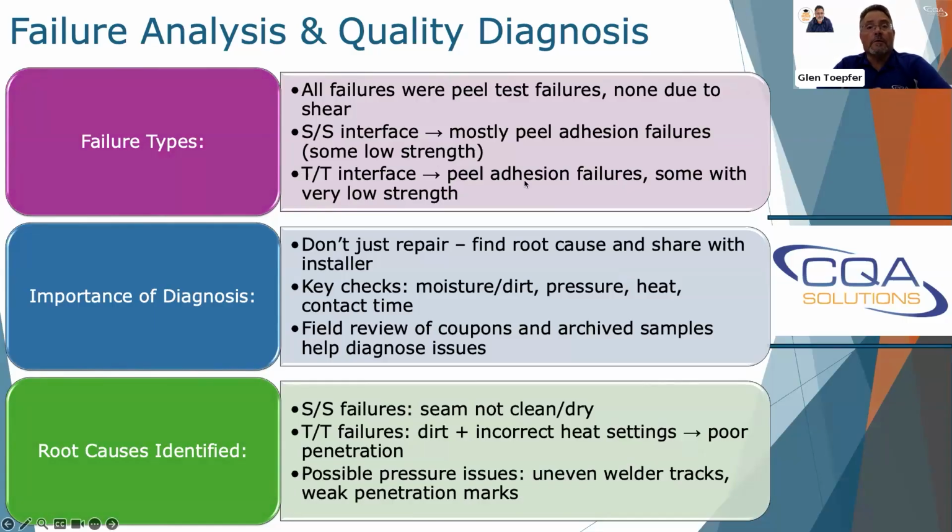And that's another thing that I like to warn people about, because we tested at Palo Verde and other sites. We tested our samples on site, and I would run the tensiometer and do the testing in the climate control. And you'd see where you start getting a peel. You might get that peel at 10 pounds. The requirement's 91 pounds for strength, and it's starting to peel at 10, 15 pounds, maybe it goes up to 20 pounds or something, then the peel stops and it gets its strength and it exceeds the strength. And, is that good? Is it not good?